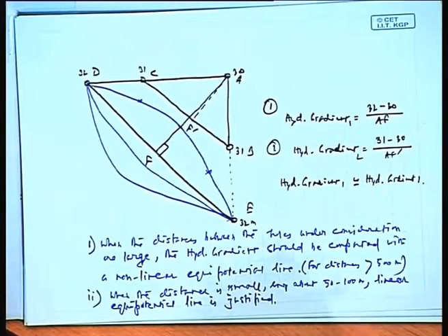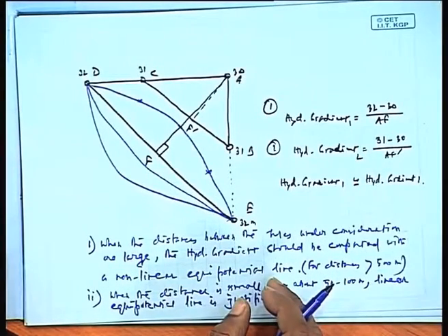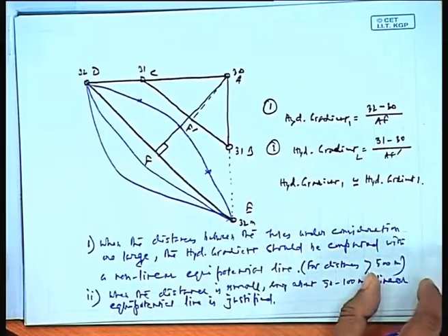So essentially it becomes an engineering decision as to how to compute, but the method of computation remains the same. That is, the change in the water head divided by the distance. In almost all cases it is the perpendicular distance that is under consideration.